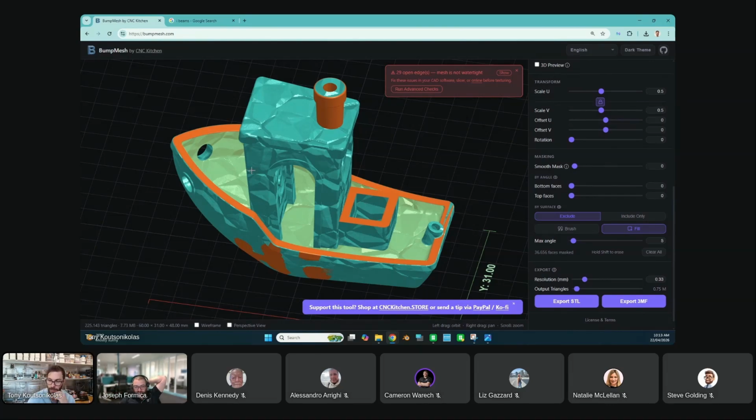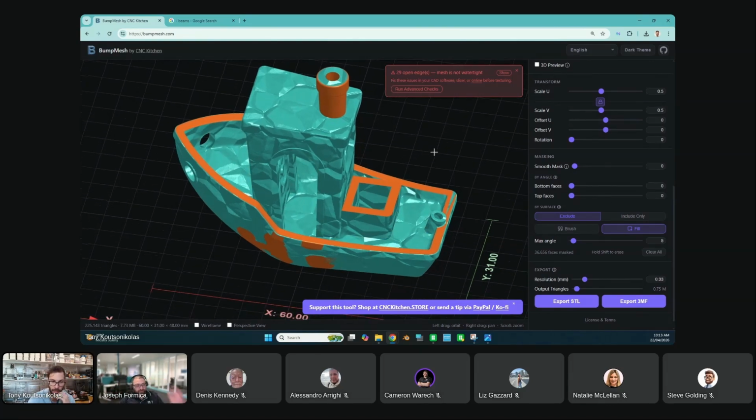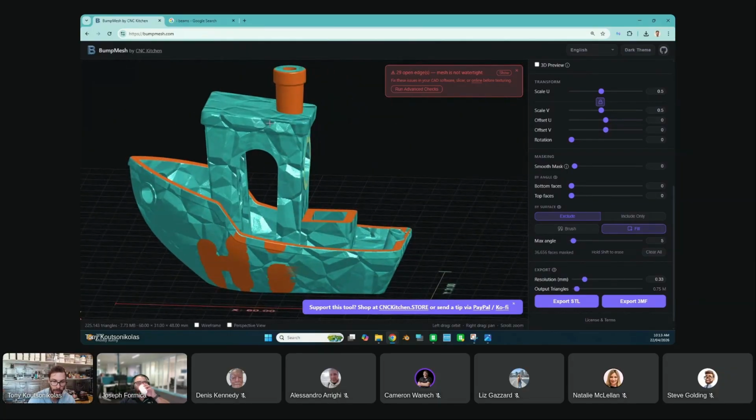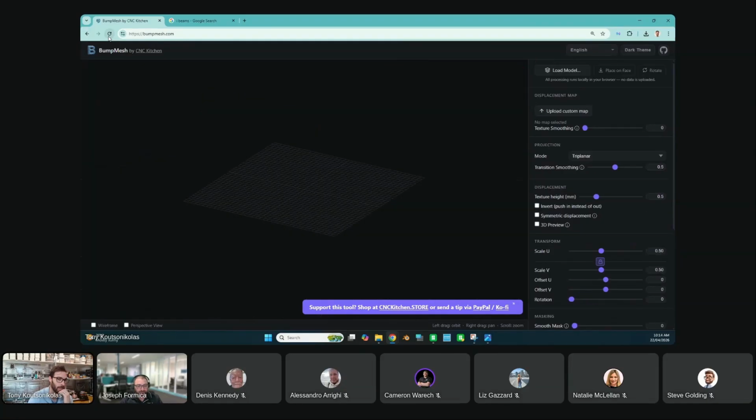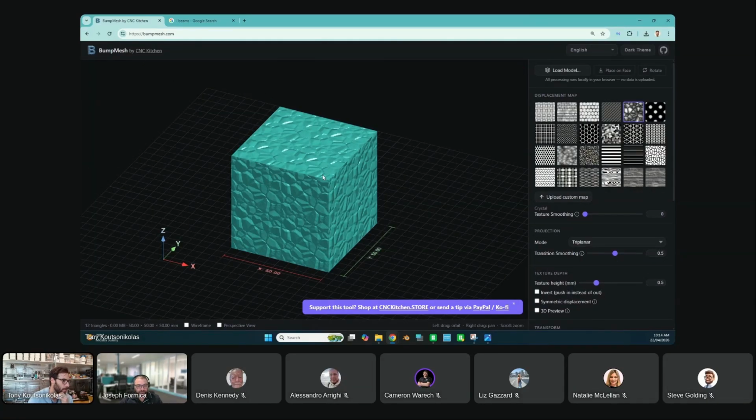Yeah, there's a lot of different little settings here. The other one is when I imported this, especially when it was a cube. Each face of this cube is made up of 2 triangles. When you design a cube and export as an STL, a lot of the time those programs make it as simple as possible to describe the shape, so it will be made of 2 triangles. If you try to apply a texture, what actually happens is it's got to edit every single triangle. It can only make a triangle go up or down. That's what a texture is like when it's applied.